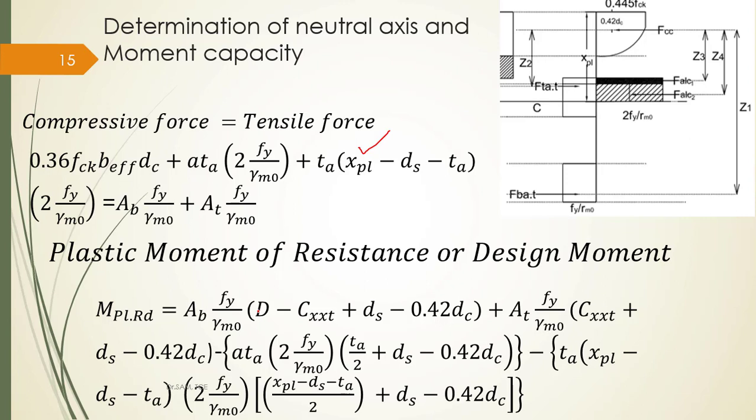If I know the moment of resistance, I can check it with the applied moment. If the moment of resistance is greater than the applied moment, then my section is safe to take the applied load during the composite stage.